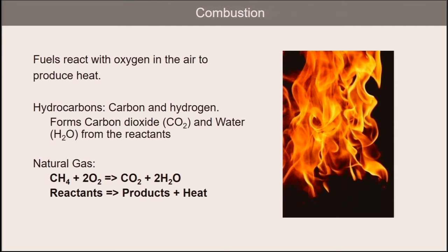So if we take this gas, or any carbon fuel for that matter, and volatilize it, a chemical reaction results with the hydrocarbons combining with the oxygen in the air to produce carbon dioxide and water. Now, the higher the CO2, the higher the combustion efficiency. And stated another way, the lower the excess air, the higher the efficiency. And we'll talk about that a little bit later. And then what you also see on the slide is that besides carbon dioxide and water being formed, we also produce heat.